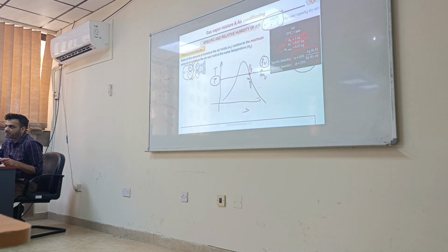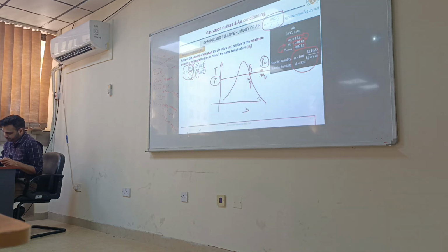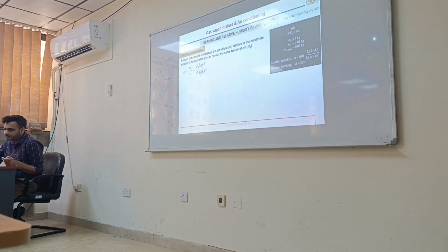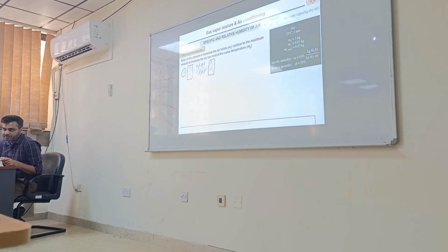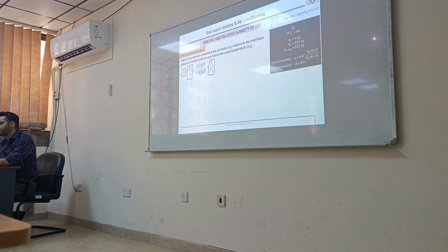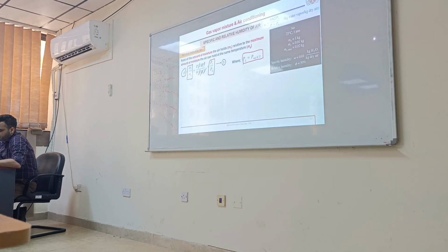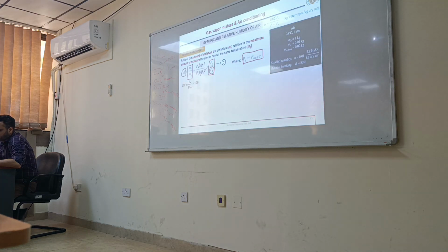This ratio is called relative humidity, at that particular temperature. Now volume will cancel, T will cancel, because it's vapor. So relative humidity can be defined in terms of mass or in terms of pressure, but only vapor or water. That is relative humidity, where Pg is actually Psat at that temperature, this Pg on the saturated curve.